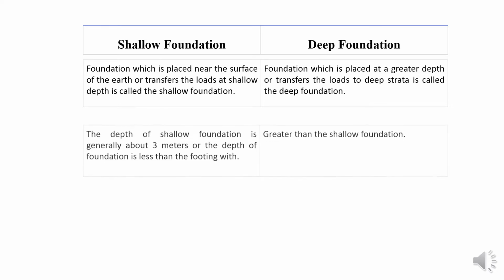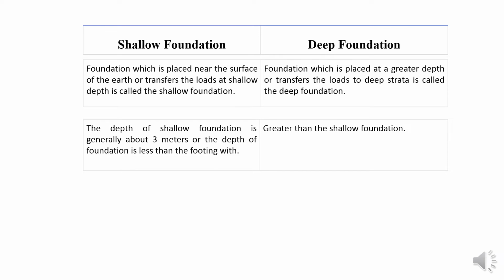Based on the depth, the depth of a shallow foundation is generally about 3 meters, or the depth of the foundation is less than the footing width. A deep foundation is deeper than a shallow foundation. For a heavy structure, normally we will go for a deep foundation.